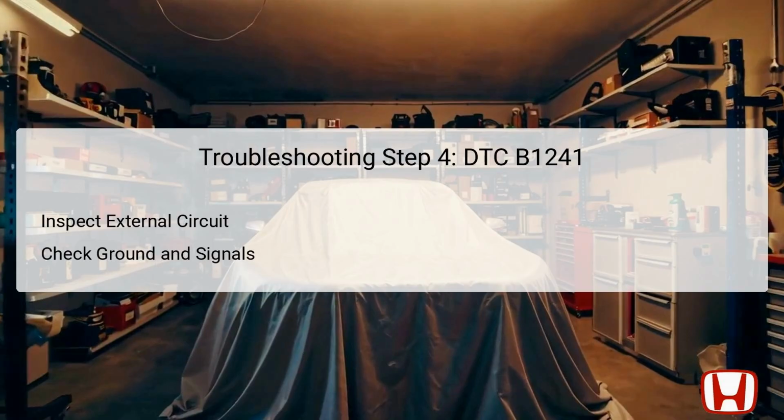Any greater readings would indicate an open circuit. An appropriate troubleshooting would involve tracing back through the wiring harness to identify any breaks or damaged areas. Also, perform shorted-to-ground inspections to confirm that there are no unintended grounding issues that would disrupt normal circuit operation.